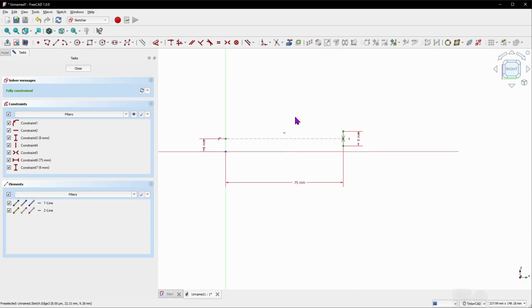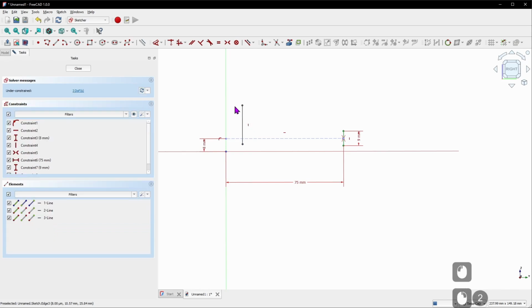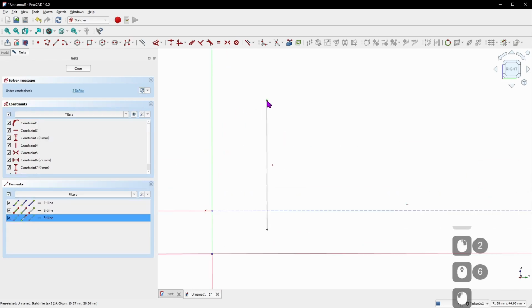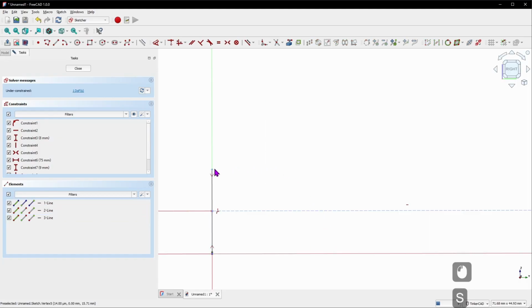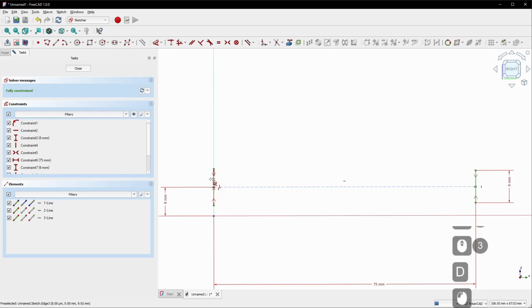Let's go ahead and create the front of our lure. We'll grab a line again. We will look for that symbol that now looks like a vertical bar. And I will get out of the tool, select that point, and that point, and use the symmetry constraint again. I used the hotkey on my keyboard that time. Let's distance this at 12.